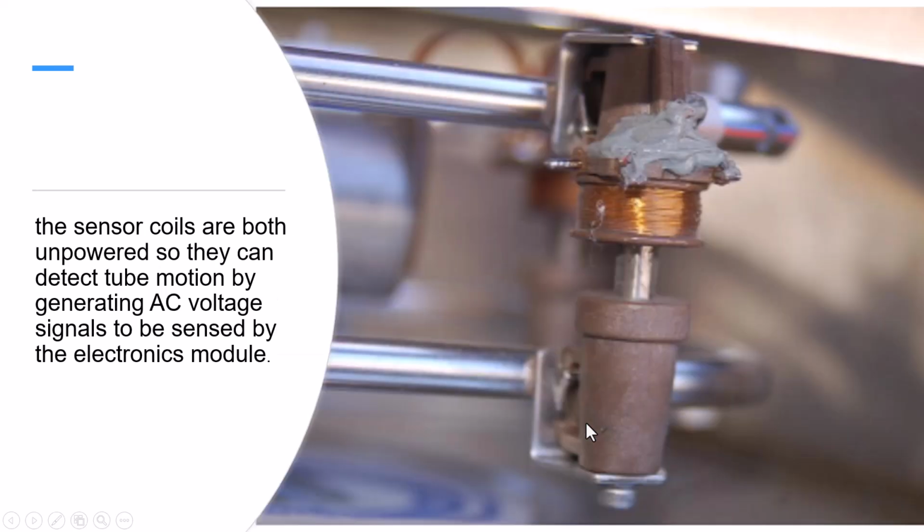The sensor coils have no power, because they detect the tube motion. The tube motion creates an AC voltage signal to be sensed by the electronics. Here the tube vibrates and creates an AC signal, so this sensor sends the AC signal to the electronic board.